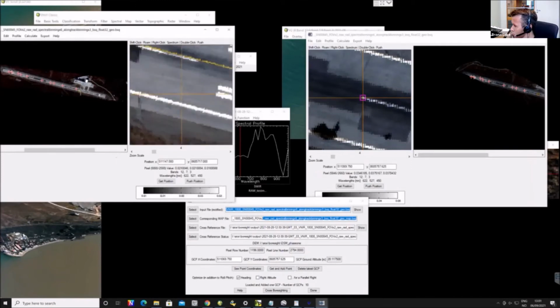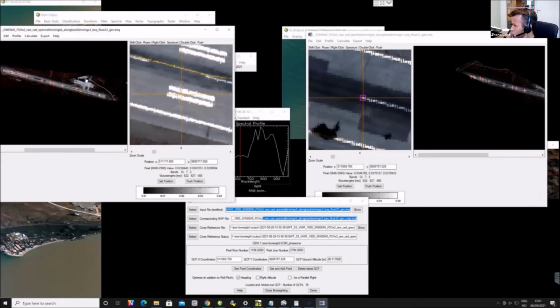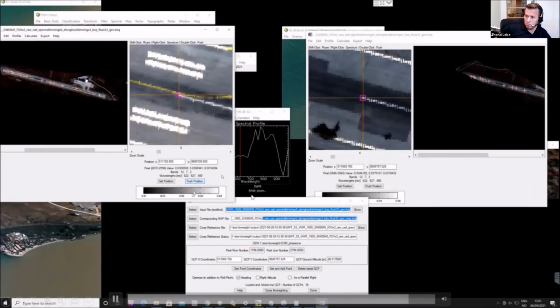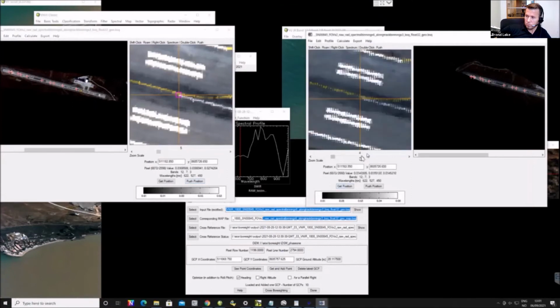But the biggest problem is actually that it uses a geoid for height reference that is not one of the typical ones. It's a custom one for Svalbard, and we haven't looked into the differences between the geoids. There's a few meters difference between those. That will cause a shift in the overlapping region. But that's why it's extremely important to have full control of the height reference, in addition, of course, to the projection.